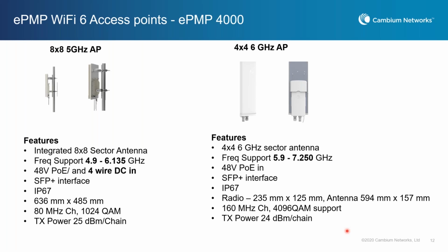Great question. So I think the way to think about this is the following. 5 gig is a congested band, where MU-MIMO benefit is desperately needed, because you may not achieve the highest modulation, but you want to go after the advantage of multi-user MIMO, i.e. 8x8.